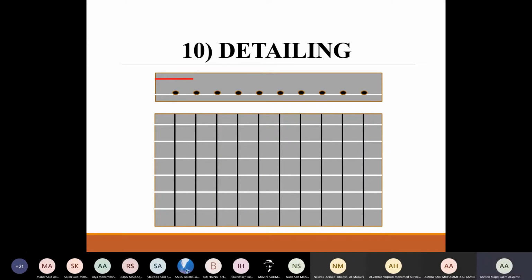This is representing now X negative according to whatever shape once again we have drawn. Now, of course, since there is X negative, slabs are two sides reinforcement. So there should be a Y negative as well, even if it's minimal. So we have drawn the red color, which is representing now X negative.